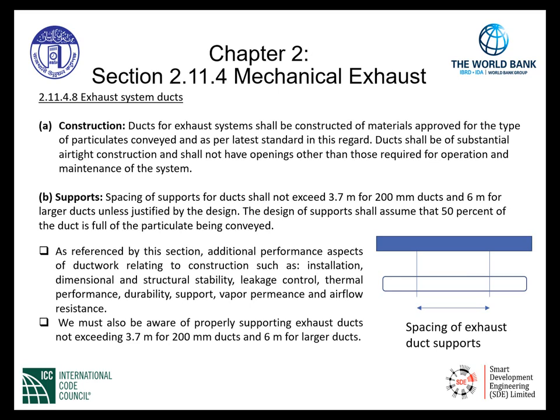So as inspectors out in the field, we must verify that the ducts have been constructed of approved materials as designed and the spacing of supports do not exceed the maximum intervals provided in this particular section.